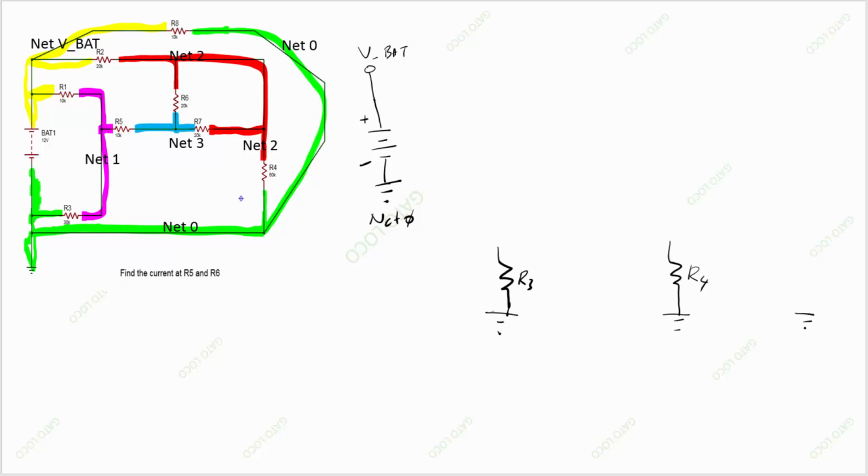And now I'm going to draw them separately to isolate them so I can visualize the circuit. So this one goes here. Let's see if I can attach R8. R8 connects to VBAT. So here it is. We're going to do VBAT here, and that one connects to R8. So R8 is done. Let's finish with what else connects to power.